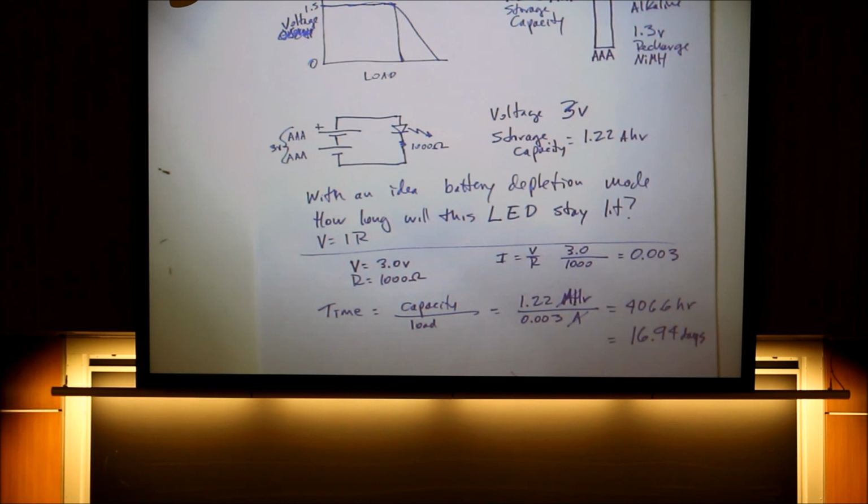Question? Does it matter the resistor is after the LED? Good question. So technically, the formula is the same, right? And some designers put it before, some put it after. So the question is, which one is better? The question is, because it's after, does that mean it doesn't actually do anything? Well, no, it will draw the same amount, whether it's before or after. Does it have a purpose? Would it be better to just put the battery connected straight to the LED?